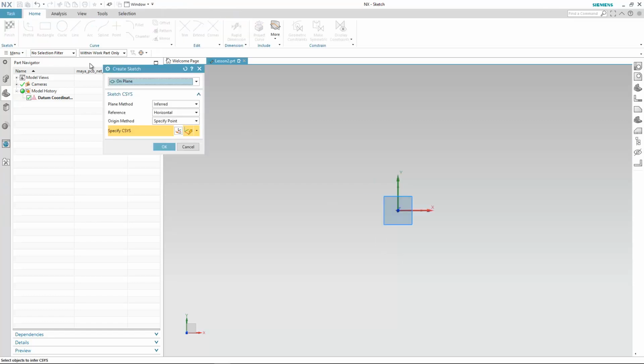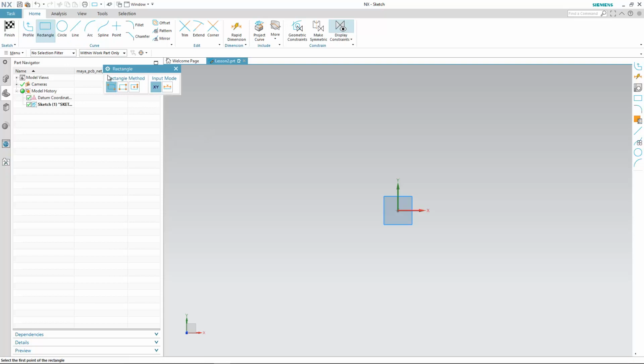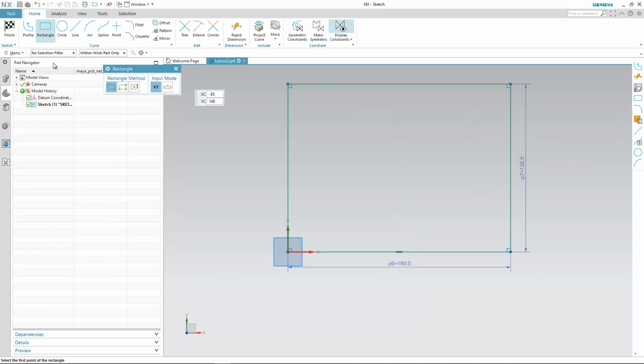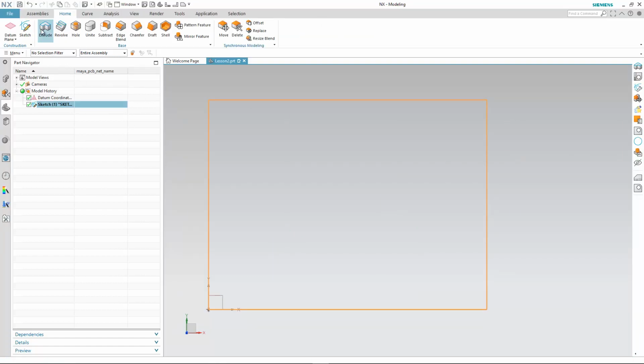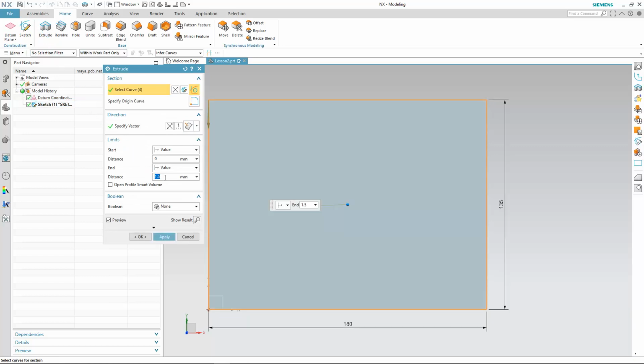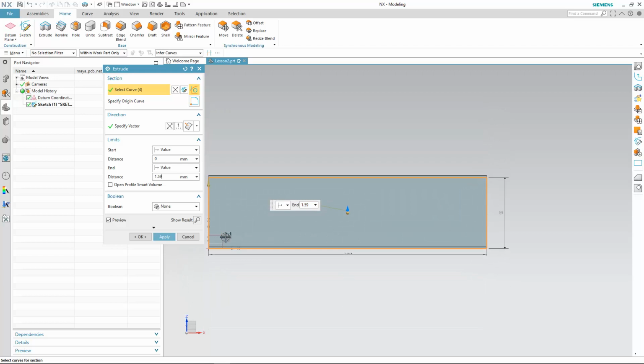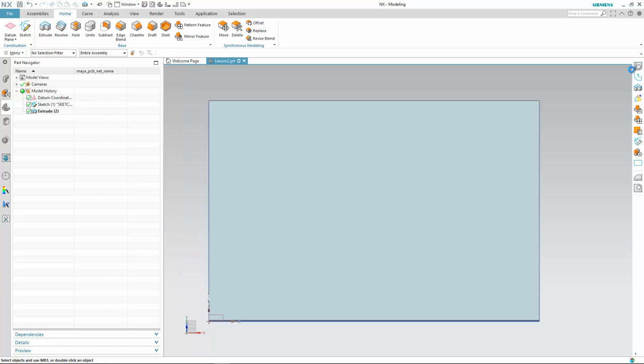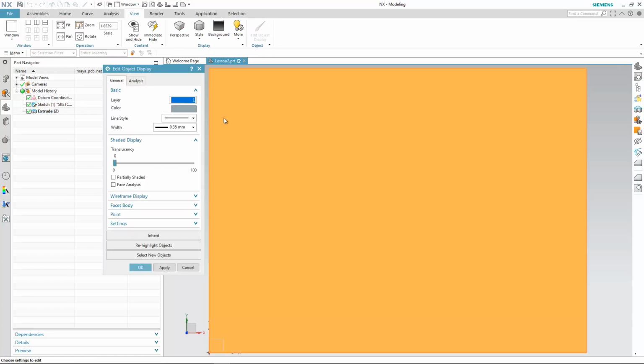The board geometry and thickness is essential in properly propagating the mechanical constraints to the electrical designer. In this example, we will create a new board outline. We'll do this by creating a sketch that's 180 by 135 millimeters. We will take that generated sketch and extrude that element to 1.59 millimeters, which matches our Xpedition stackup.